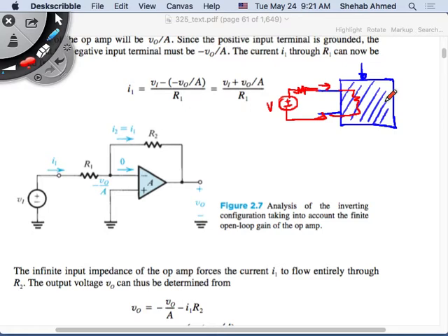How does a voltmeter work? You put it in parallel, but what is it going to do? It's obviously going to draw current, but the voltmeter, in that case, will be like an infinite impedance. It's a device that has a very, very high impedance, so it will draw very little current. With this very little current, applying the current divider rule, you will know the voltage across the resistor that you have in parallel.